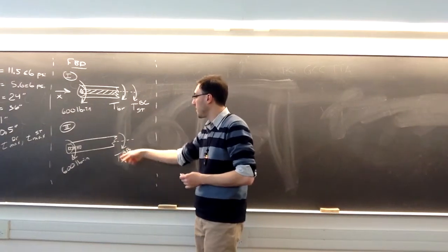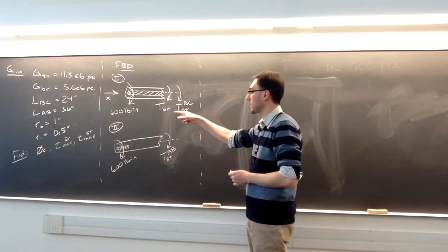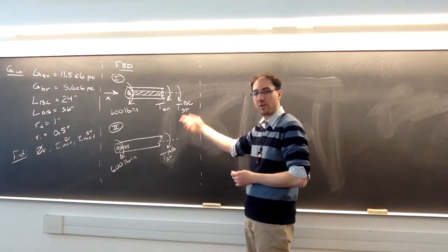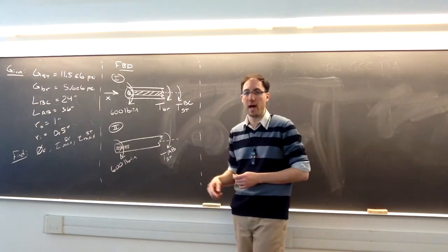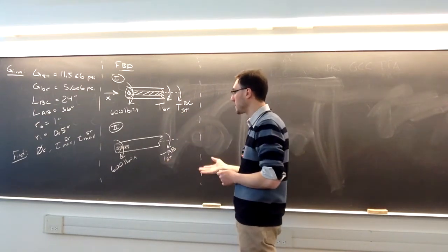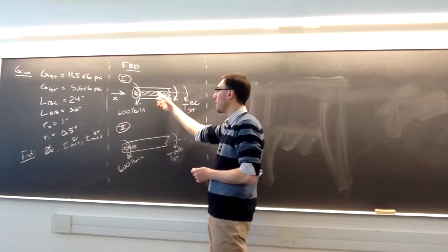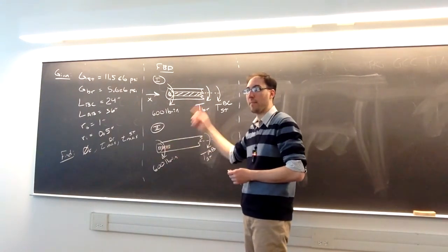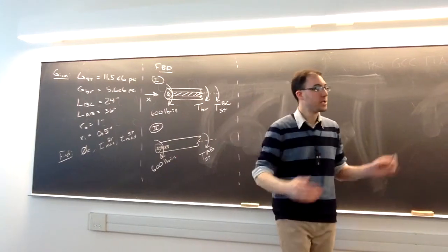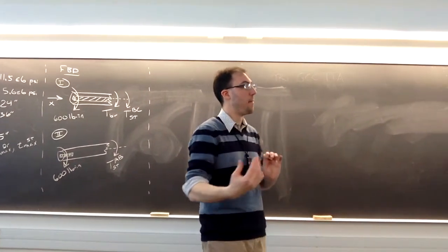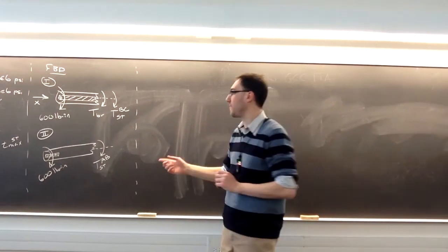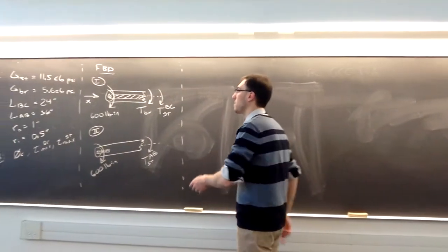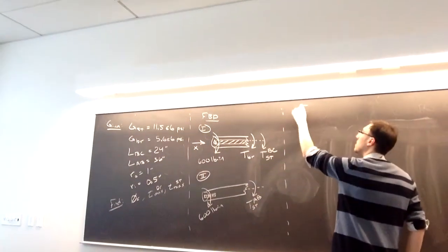I do have 3 different internal loads here. I have my external load and 3 internal loads, or 3 internal torsions, in the 2 pictures that I was able to get out of this. So it is statically indeterminate in that I can only get 1 equation from each free body diagram, but I have 3 unknowns. So it's not constrained between 2 walls, but I need additional equations to find out what these internal loads, or these internal torsions, are.